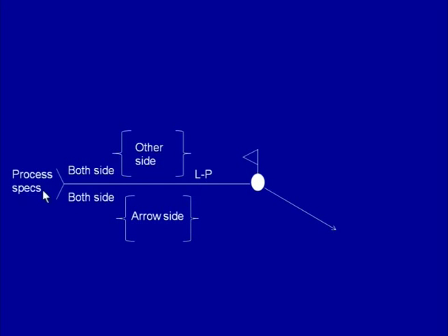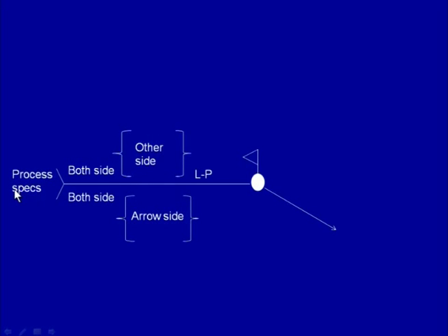Then, on the back side, at one end of the reference line, we can have the tail, which basically has two lines, and this tail is used to show information about the welding process to be used or the specific welding parameters or specifications which should be used for developing the weld joint, like whether the weld joint will be of the partial penetration kind or the full penetration kind.